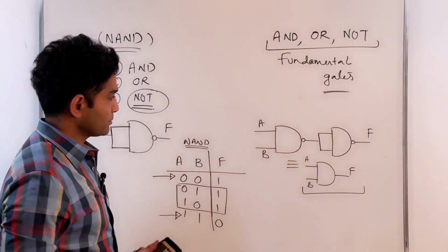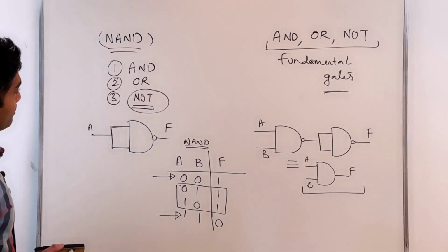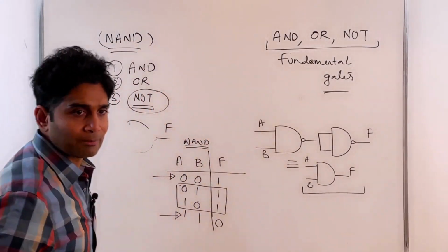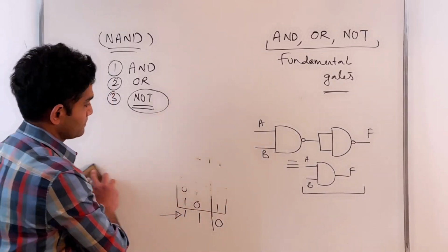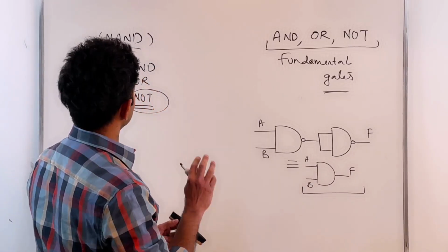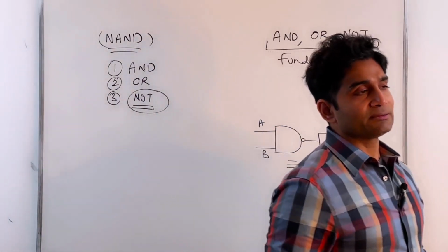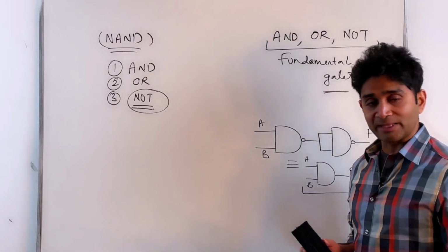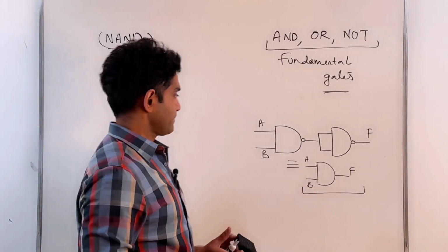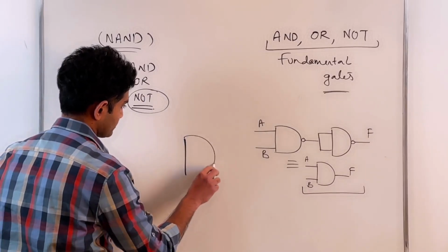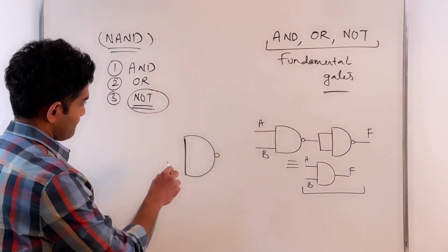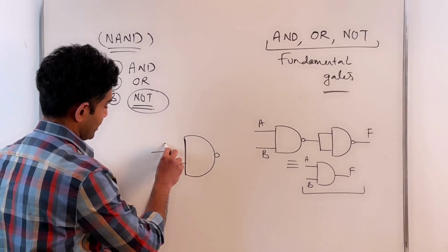All right. So that's easy enough. What about the OR gate? How do I obtain the OR operation now? Yeah, Montgomery. You do the same thing that we did with the NAND gates, but use NOR gates. No, this time I'm trying to show that the NAND is a universal gate. We still want to use NAND gates to obtain the OR operation. You take three NAND gates then. Take the first, so you apply A to both terminals of one NAND gate and do the same for B.